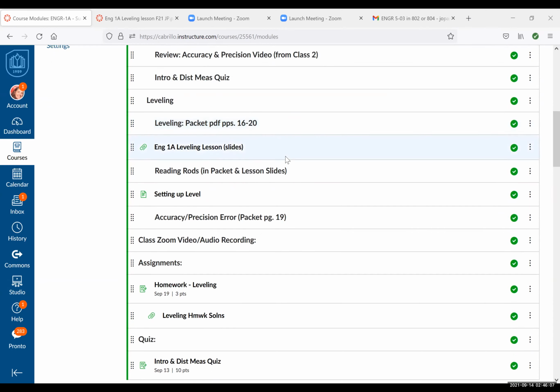So today our main focus is about leveling. And the process of leveling is to determine the elevation of points. So you will always know an elevation of a certain point that's referred to as a benchmark. And when you're shooting off that benchmark, you could then determine what the elevation is of other points.